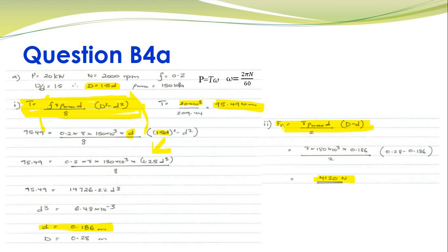Again, just keep in mind that your actuating force is independent of the friction surfaces. It means whether you have one friction surface or two friction surfaces, that parameter does not appear in your actuating force calculation. However, when you're calculating torque, it is dependent on the number of friction surfaces that you have to transfer power or torque. So in this case, n is a function of this equation.